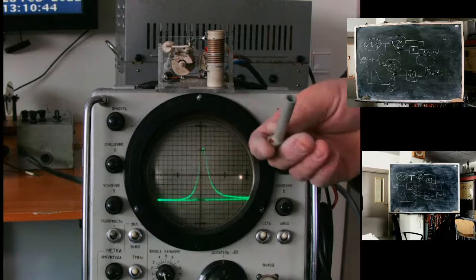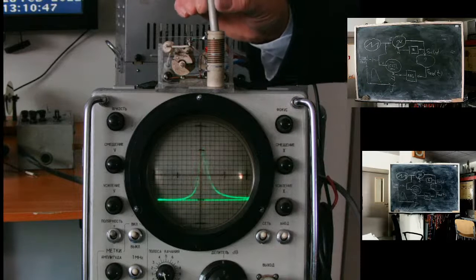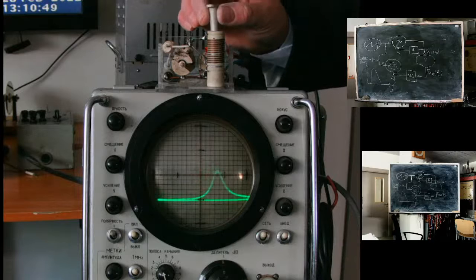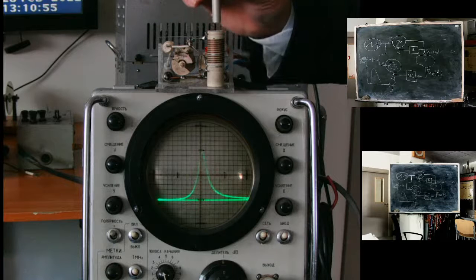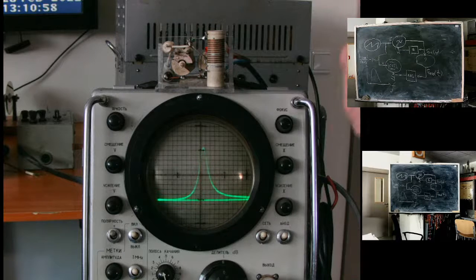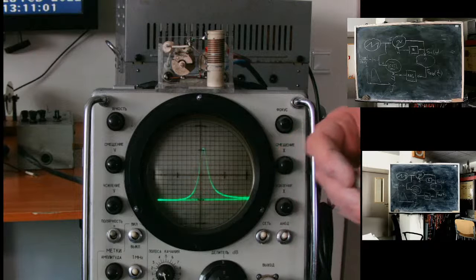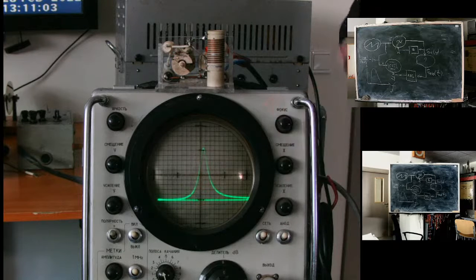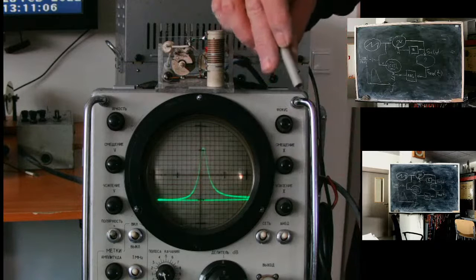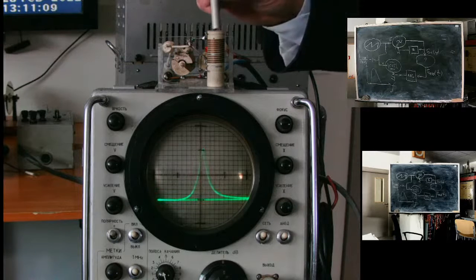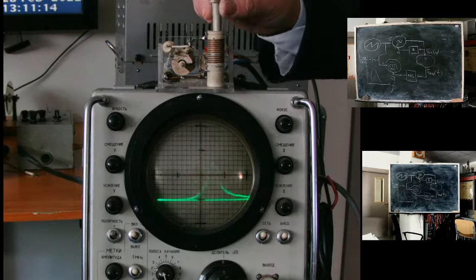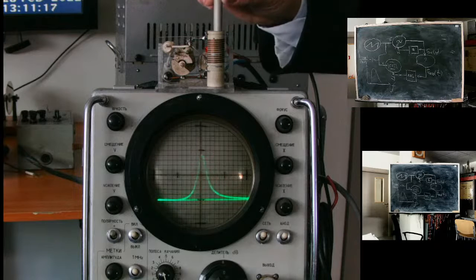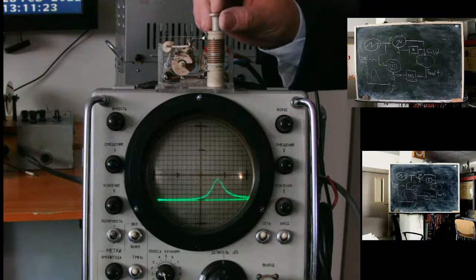It's an aluminium pipe. What will happen? Of course, losses are increased because current flows in the pipe. But also, you see, the introduction of the short circuit object, in fact, only the surface of this pipe works, but it's a short circuit and it decreases the magnetic energy stored in the coil. And you see, losses increase, but frequency decreases.